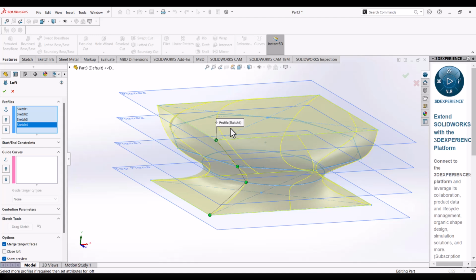So in that case, you have to use a lofted boss. You select sequences of planes, then you draw each section. You cut through this section, this is how it will look. You cut another section, this is how it will look. You cut another section, this is how it will look. Then you join all these sections together. Okay, so now let me accept it.